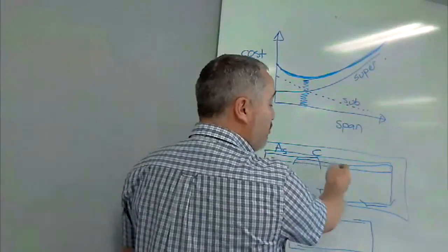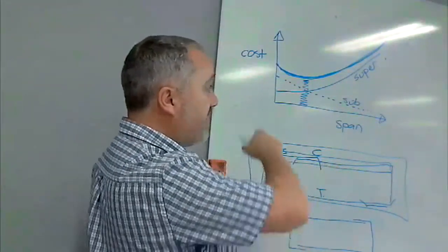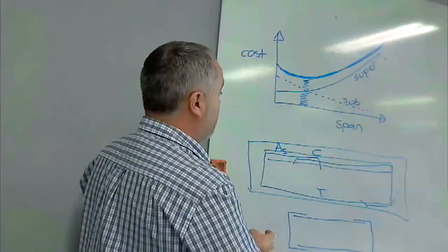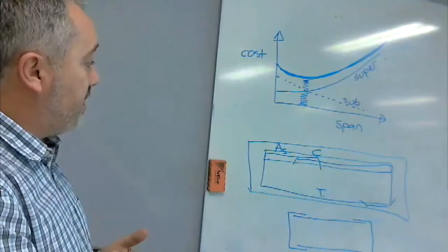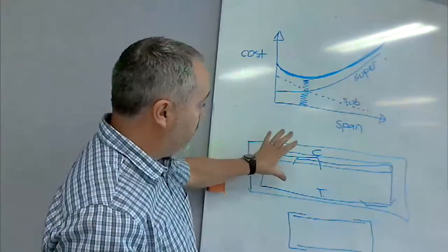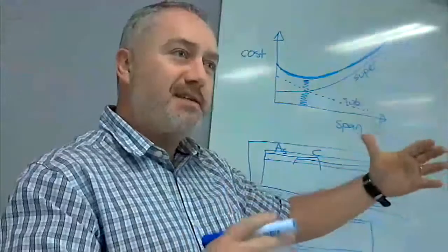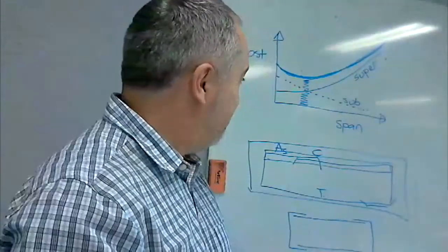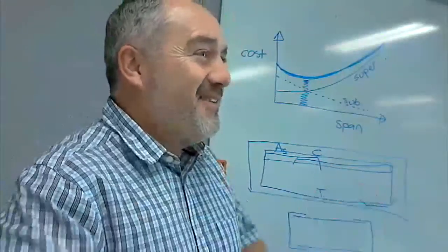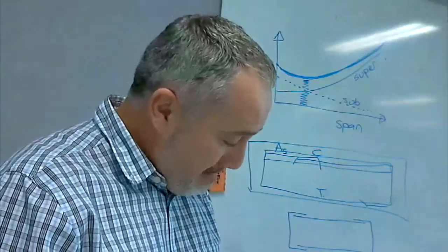That's your compressive steel. You've always got to put steel in the top just to make the cage go together. But it's all about the area of steel, whether you choose one type of bar over another. I remember the AutoCAD guys used to have pages of all the different codes for steel. Unless you do it all the time, I never really knew myself.